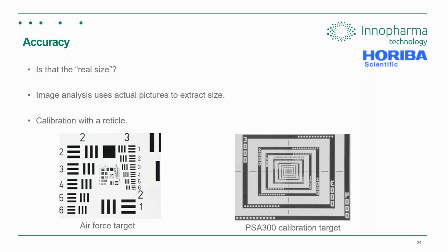So essentially what you have here is you'll point your camera system at this, you'll look at the bars and lines that are getting progressively smaller and smaller, and your image system will have a point where it can't see a gap between these lines anymore. The lines will become blurred, and that's your level of resolution, among other things.